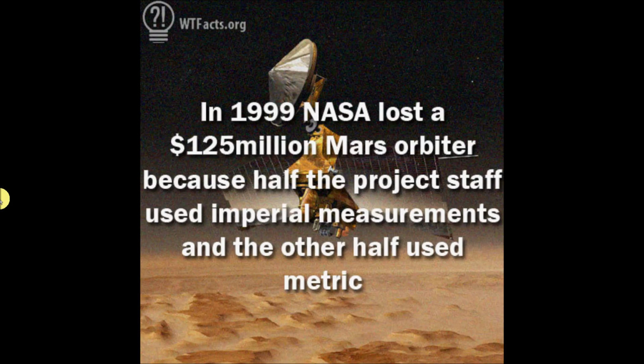You have to understand the units, and this is going to affect you on your assembly. Sometimes you may be building something in inches, then you import something in millimeters, and then you realize you have to start over because sometimes the scaling tools don't work as well as you like them to. So remember, on every file, double check the units that you're using. I'm going to teach you how to set that up once we get to that stage of the program.